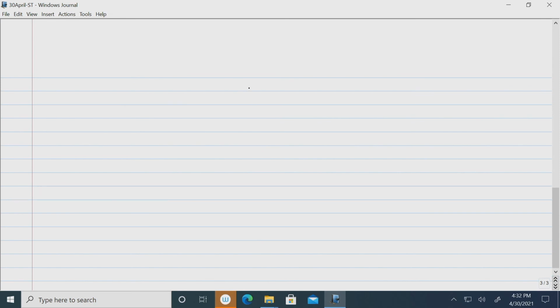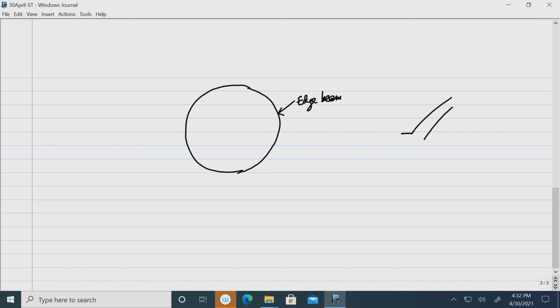If we see the plan of the roof dome, there is a circle, and this is your edge beam. Now, you can see here that near the edge beam the thickness is increased. The thickness earlier was 100, now here the thickness is increased. So, the increased thickness may be 125 mm. I am proposing the thickness at this edge is 125 mm compared to 75 mm at the